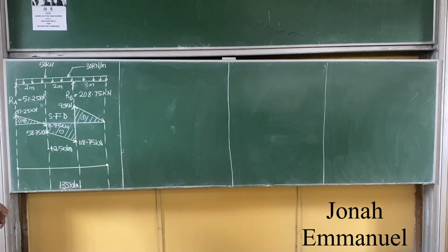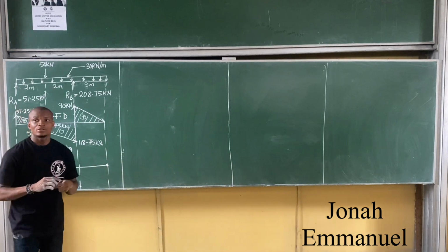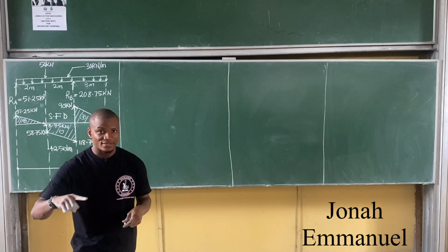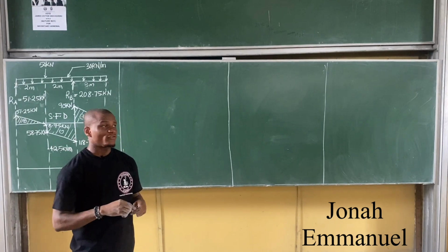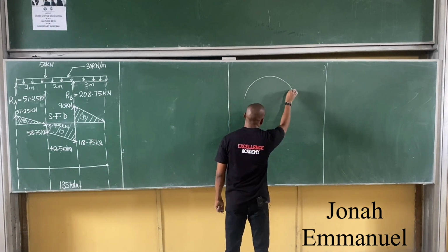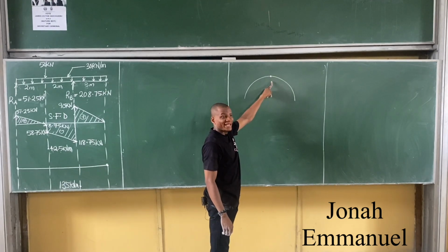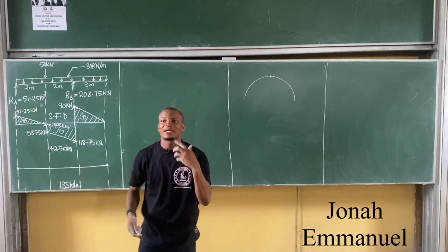Now look up this. Look up. Next up now it becomes a bit technical. Now I said if you're doing shear force for just point loads, use what there? Straight lines. For you there, what is there now? Curves. Become a curve. Now if you look at it, if I'm doing a curve of this nature, there somewhere must be my apex point. I must have an apex point in my curve.